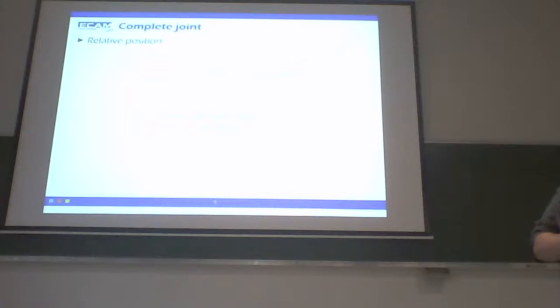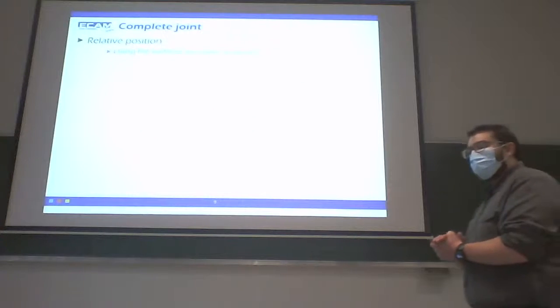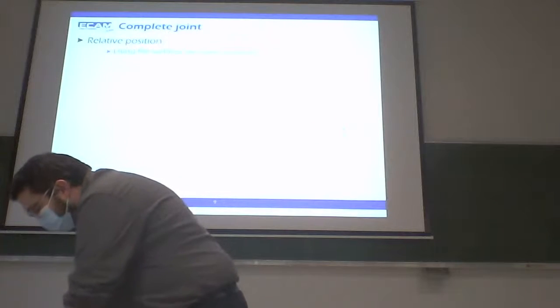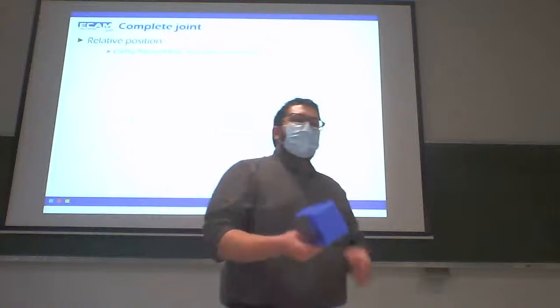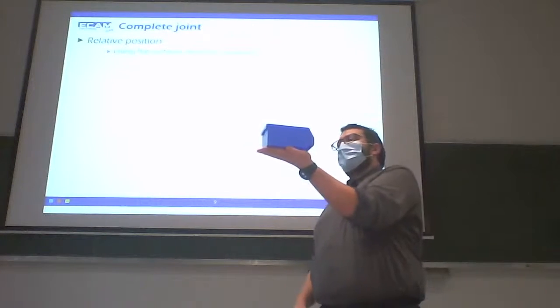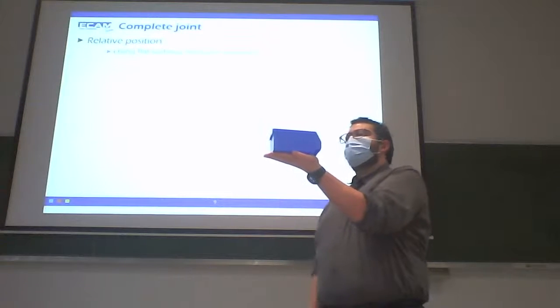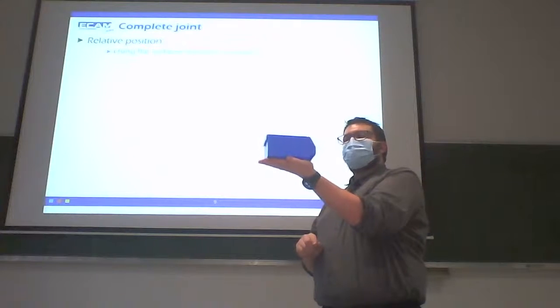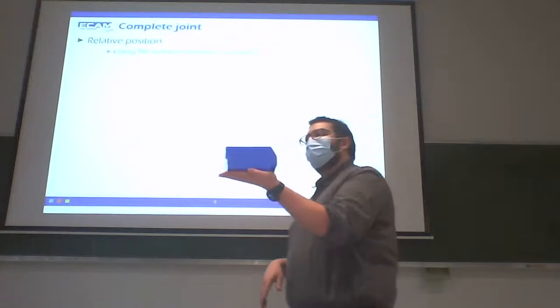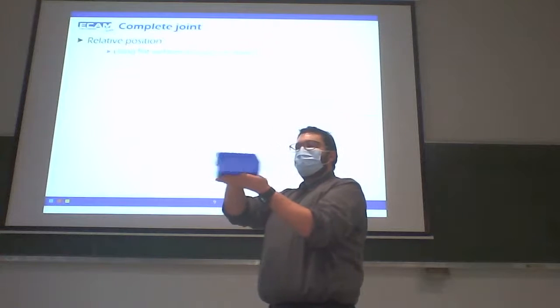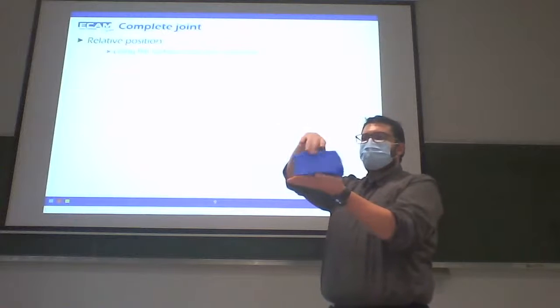Example of these two main solutions. When I use flat surfaces and pins or dowels: if I use two flat surfaces, between my hand and the box, here I create a planar joint. With the contact of the two parts, I have only 3 degrees of freedom: one translation, a second translation, and one rotation.